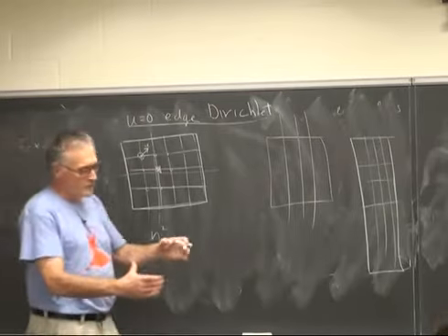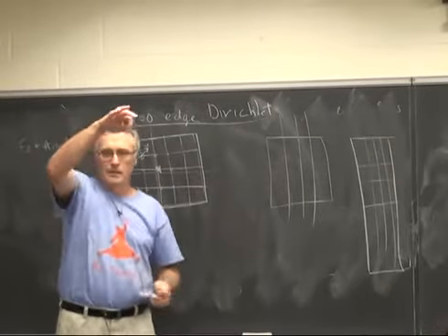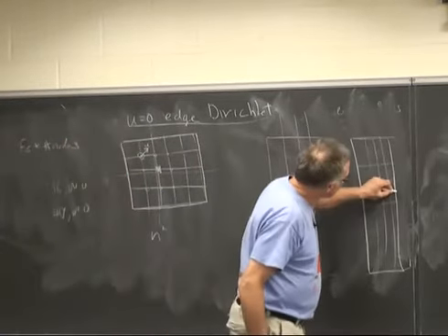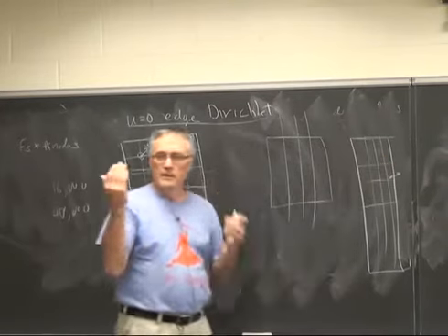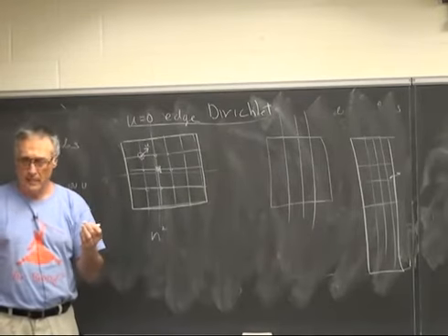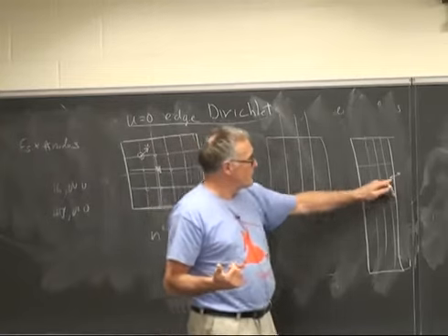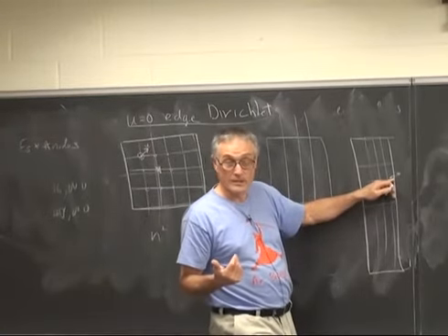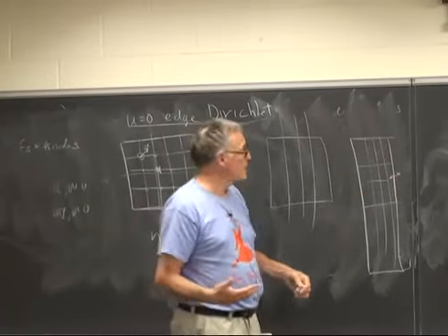But if you just take a piece of steel and hang it in the air and smack it like a gong or like a chime, then the edges are free to vibrate. The edges vibrate, but no energy can pass by the edge. And so the derivative, the slope, has to be 0 at the edge because there's no restraining force on the edge, steel being much stiffer than air.